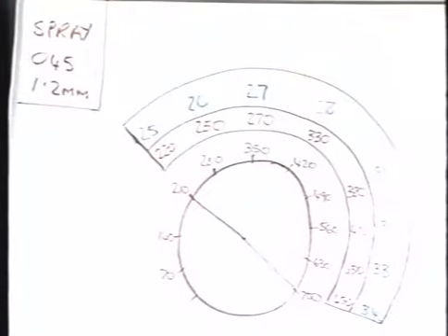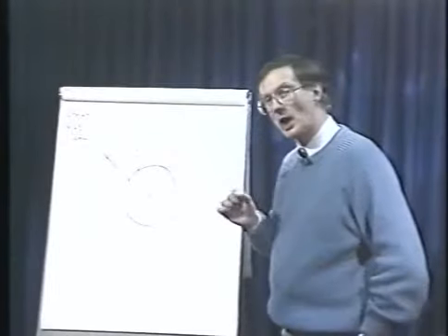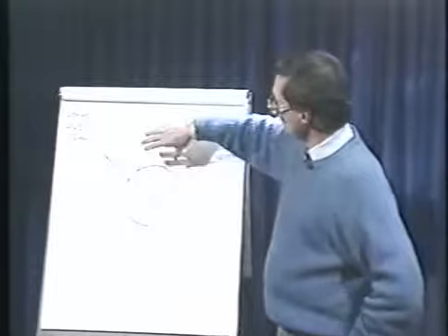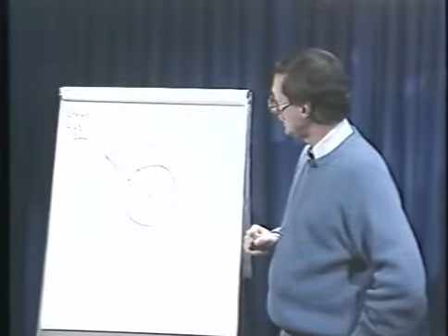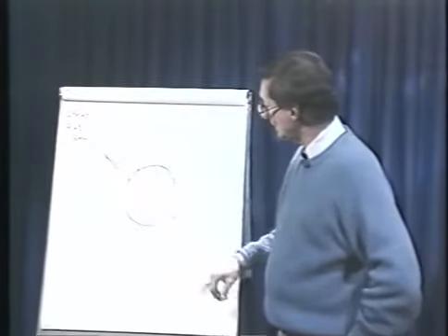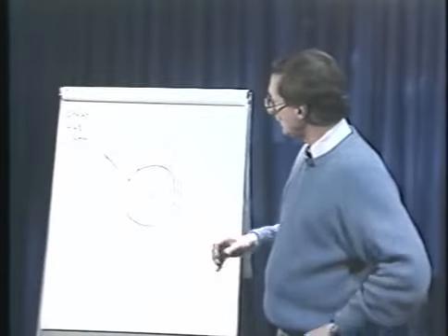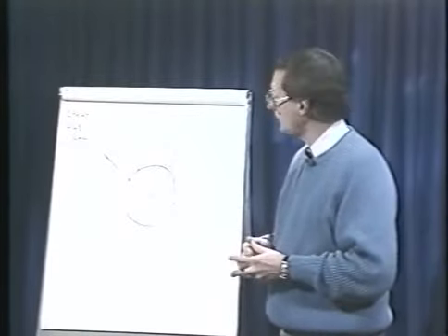As you can see, the wire feed range is now extended from the 10 o'clock position to the 5 o'clock position. The current, we need at least 220 amps, a lower voltage, 25 up to 34 volts. 045 is the most suitable wire, not only because it's a lower cost wire than the 035, but also because of this extended current range and the achieved deposition rates.